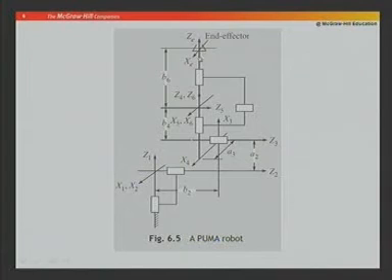The 7th coordinate frame, in this case, I have indicated as the end effector coordinate frame. So, x e stands for the 7th coordinate frame or end effector coordinate frame, and z e is the end effector coordinate frame z. So, x e is parallel to x 1, which is why it has 1 0 0. z e is parallel to z 1, so that is the reason it has 0 0 1.